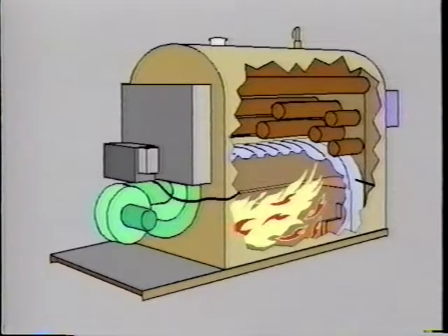The firebox boiler has water legs supported by stay bolts which extend down the sides of the boiler. The stay bolts prevent the sides from bulging from pressure in the boiler. Firebox boilers are used for low-pressure steam or hot water heating applications. Sizes of the firebox boiler range from 12 to 337 horsepower and are package boilers.